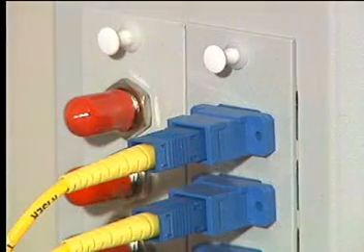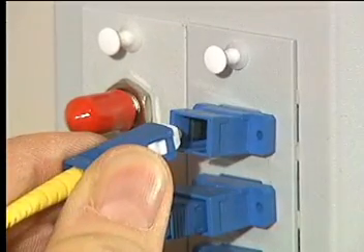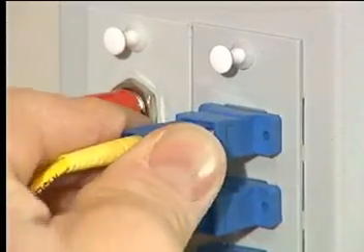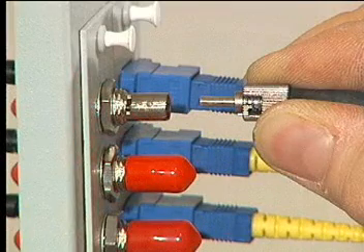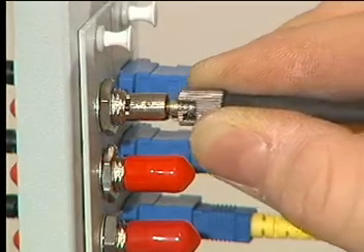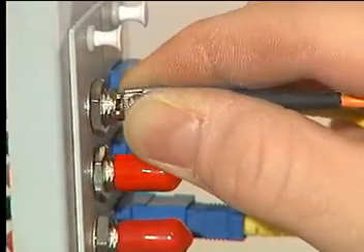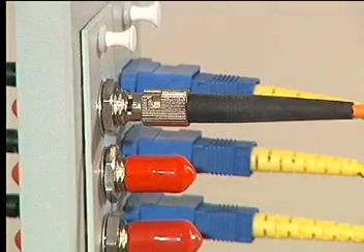In order to keep connectors clean and undamaged, it is very important to observe correct handling procedures. Pay particular attention to alignment while mating connectors to avoid dragging the optical surface along the inside wall of the coupling sleeve. Hold the connector so that the ferrule passes straight through the center of the sleeve.